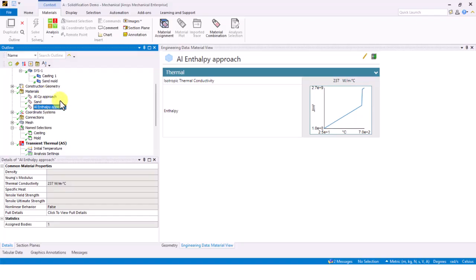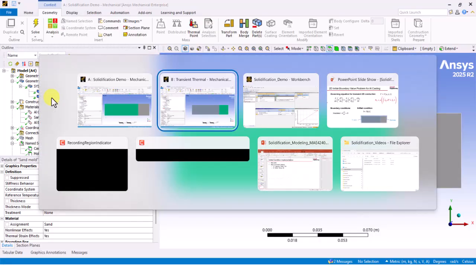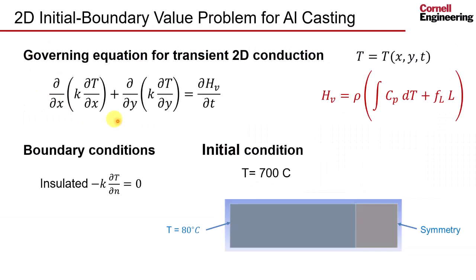These 2 should give me the same result below the solidus temperature. So if I look at this, I can now make sure that I have the right variation, and I have also assigned it. So that's what it'll look like when you do all the inputs correctly. And so at this point, the governing equations should be specified. And the next thing would be the boundary conditions.